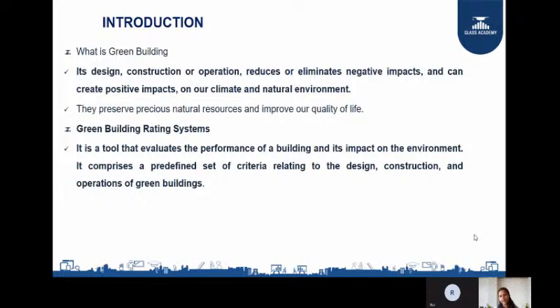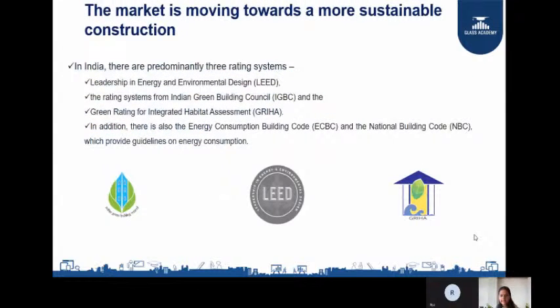So this is one comparison of the products, so you will understand why a certain generation is better than the other generation. You can see here I have taken one product from each of the generations: second, fourth, fifth and sixth. When you see the VLT column, VLT is approximately the same for all generations of product, 47, 50, 46. But if you see the solar factor column, from the second generation to the sixth generation, the solar factor is reducing drastically.